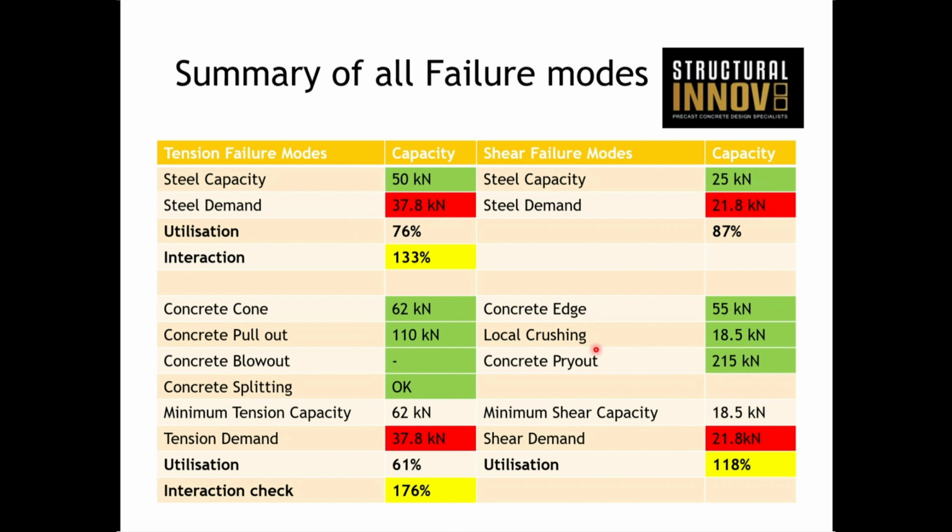So there are a number of options, depending on what's most practical, really. In the factory, you could say that you're going to use a spreader beam, engage all 4 lifters, and then all these demands will divide by 2, and that will get you over the line. Spreader beam is not always practical.